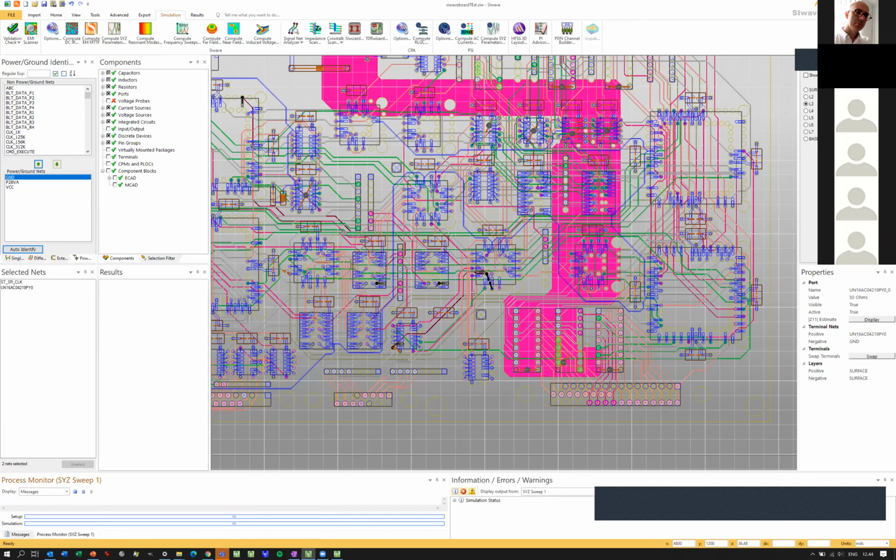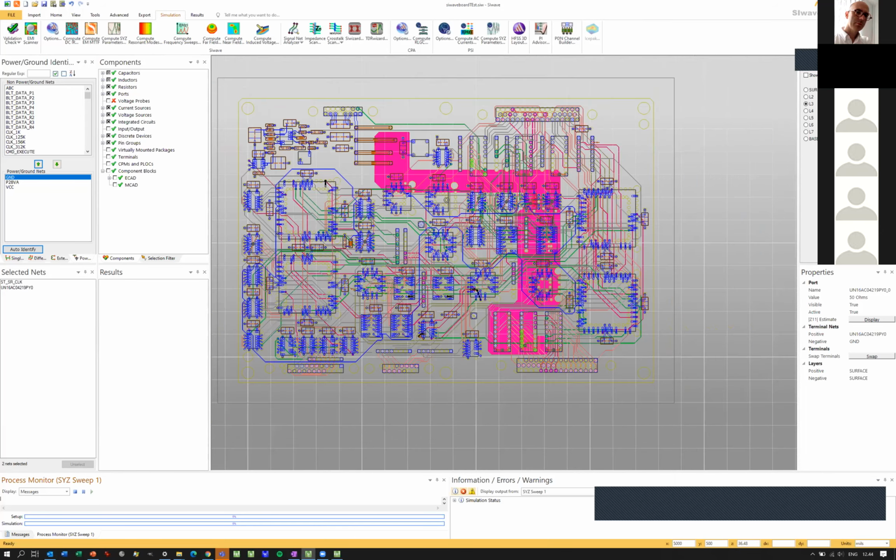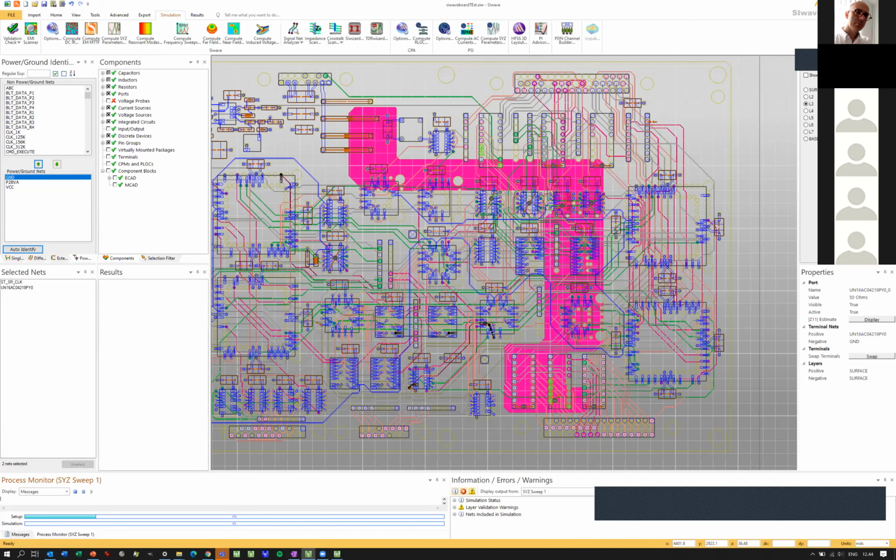Okay, yeah, let's replace the existing. So now it's doing the simulation. Basically, this is the method of moments solver, 2.5D. We are approximating every single, so it's doing the meshing for the circuit board, but it's expecting that you have FR4 dielectric, copper layer, FR4, copper layer. So it can use kind of an RLC simplification for the traces and ground and power planes between.